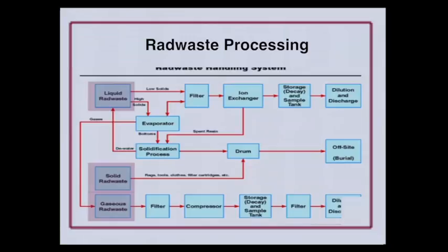And also, coming off of this, there's a dewatering step, so you're removing the liquid and feeding it back up into the liquid rad waste system. So there are some kind of crossovers, if you will, between a couple of the types. Not shown here, but the gaseous rad waste, the filter here, these two filters catch any particulate, so they're going to generate solid. And these filters are going to have to be processed, and so they would fall back up here in the solid section and be processed as solid waste. So there's a little bit of a cross there.